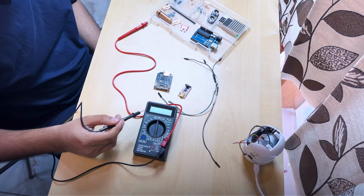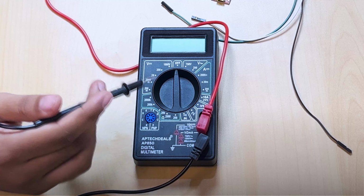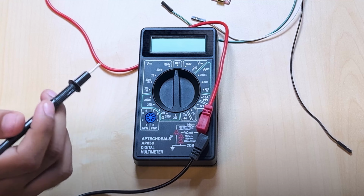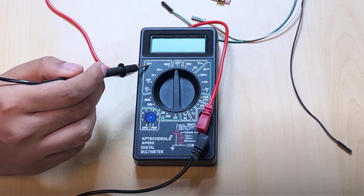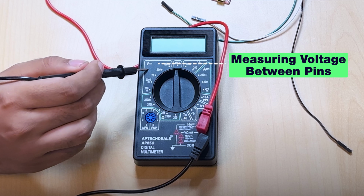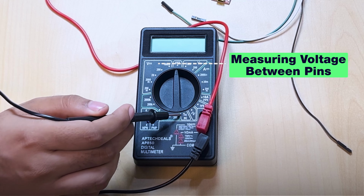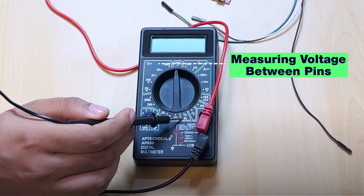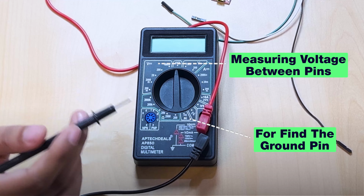On the multimeter, you will find multiple symbols, which are the multiple modes and different variables that you can test. What will be utilized for us, number 1, is this: the V sign with 2 lines, one dotted and one continuous. This will be utilized for measuring the voltage between pins. And one at the bottom right corner in my multimeter, which has a Wi-Fi symbol and a diode symbol. This will be used to test the continuity, mainly used to find the ground pin.